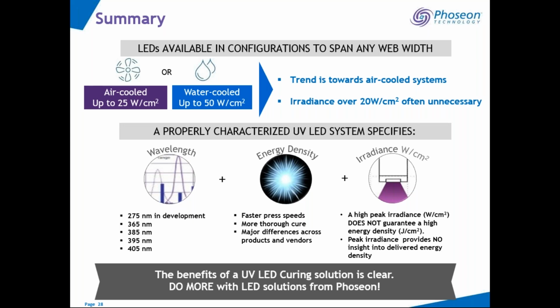So this question says, I believe that infrared can actually assist in the curing process of UV inks. Can the elimination of infrared have any detrimental effects on the curing process? So we have seen that if you keep the inks too cold, that does slow down that curing process. So if you're running on a chill roller, we caution not to keep that chill roller too cold.